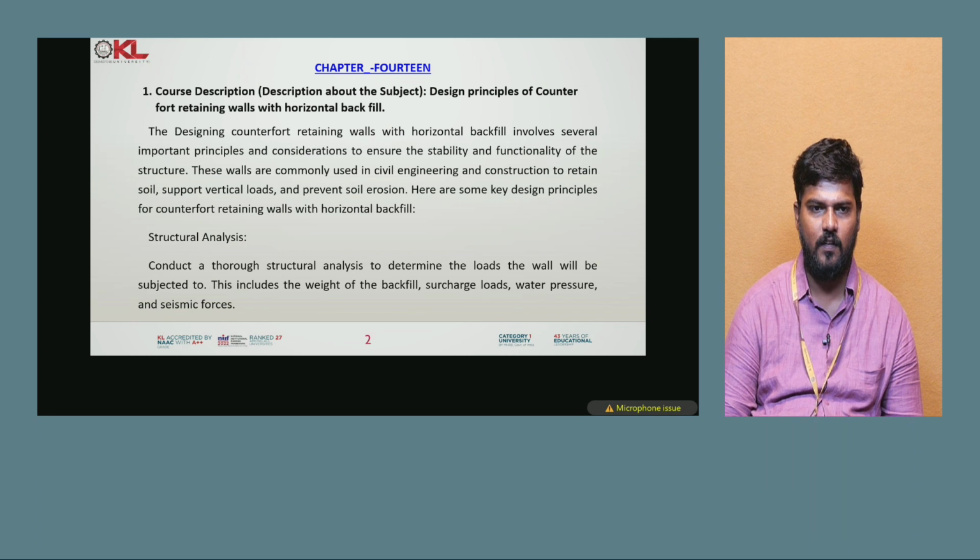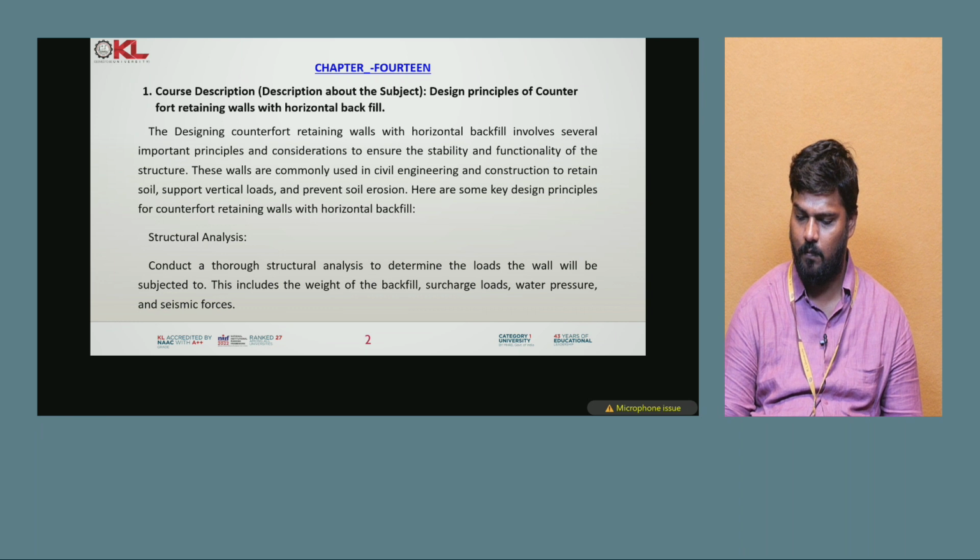Coming to the first one, the structural analysis. Conduct a thorough structural analysis to determine the loads the wall will be subjected to, which includes the weight of the backfill, surcharge loads, water pressure, and the seismic forces that are coming onto the wall.